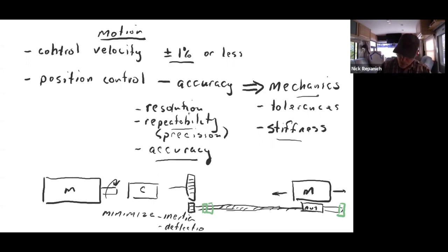You would want to look at when you turn this screw. Well, the longer the screw, the more it's doing a rotation. So the thing to keep in mind here is that as we're doing this motion profile and we're doing motor sizing, you are sizing this motor. You are assigning a motion profile, you know, accelerate, decelerate, speed versus time. You're assigning a motion profile to that motor.